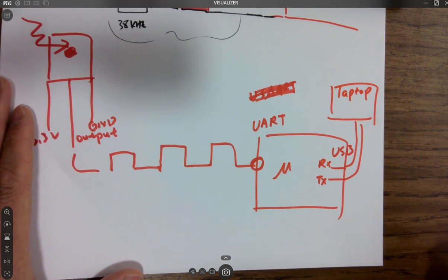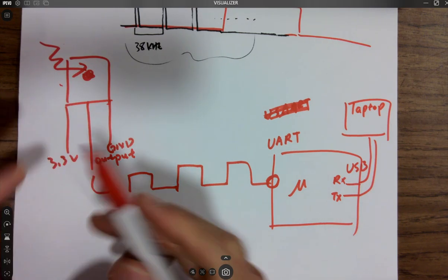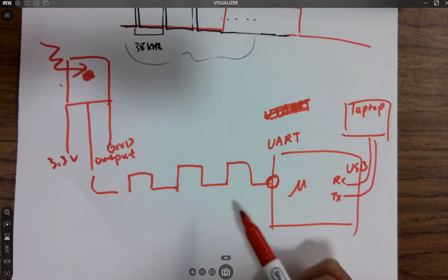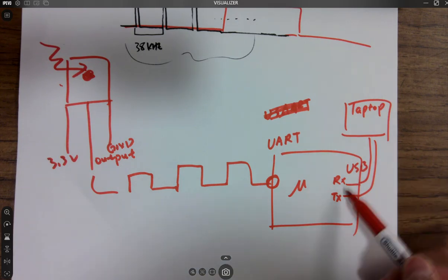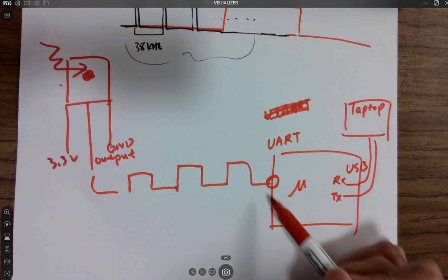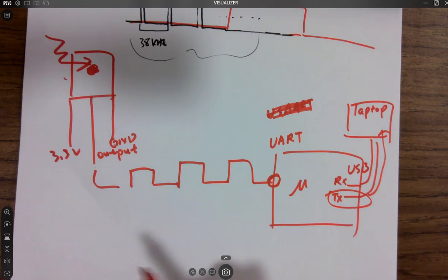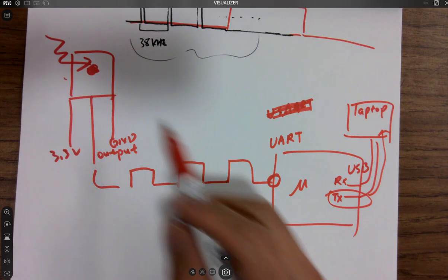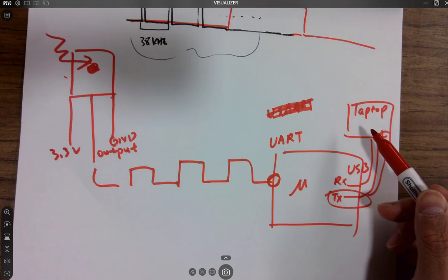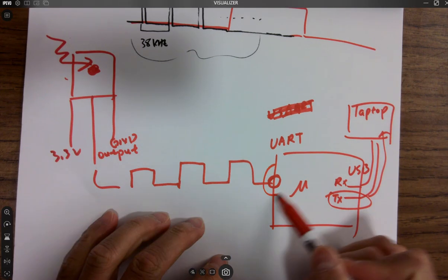All right. So whenever something is being sent and received, and we don't have a display module like an LCD or LED module on the board, there's nothing you can use to display whatever is being received. But we know that we have USB connected to the laptop, so we can directly relay whatever is being received and send it to the TX of this UART and through USB, so we can look at what has been received by the decoder through the UART serial monitor, right? And so now we have to figure out what is this port and what is this port.